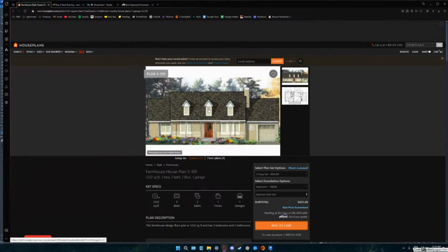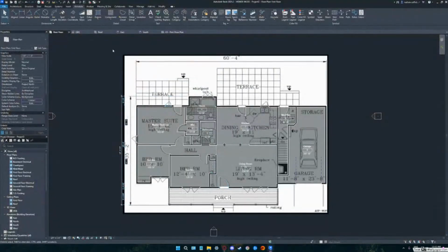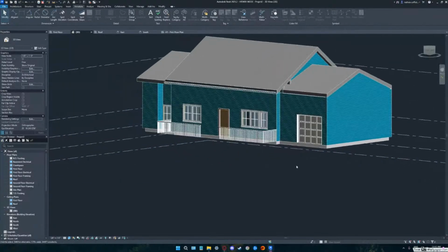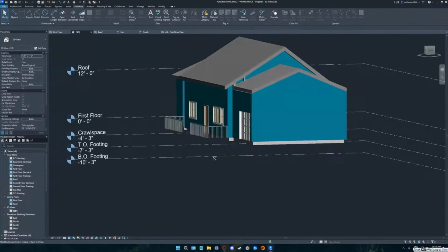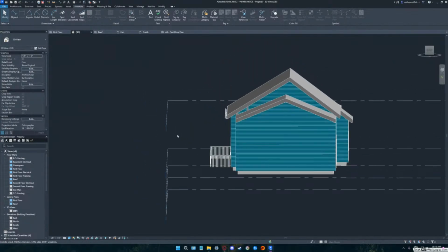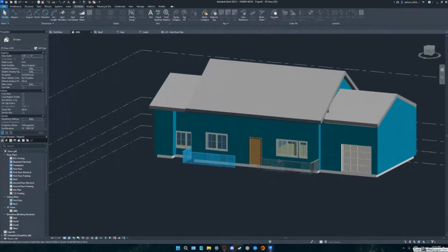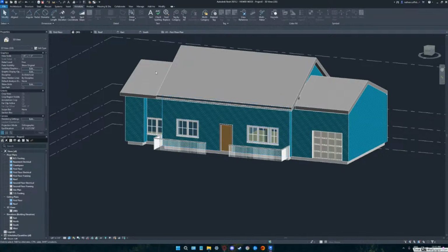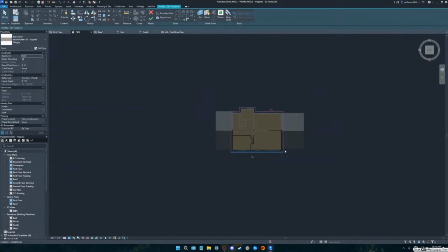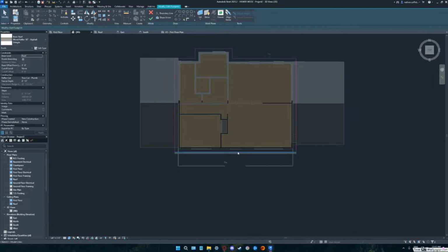Okay. And you can't do that the way you built yours. Take you back to yours. Because when you look around there, if you put your dormer at that front face, it's going to be way low down. So what we need to do is widen that roof to include that front porch. Right? And all you need to do is drag that one purple out. Bear with me.